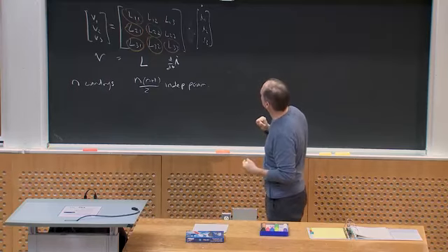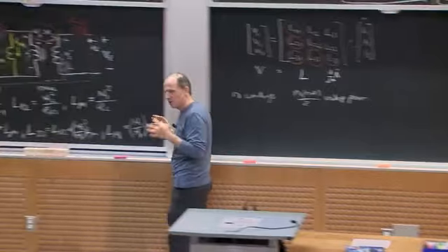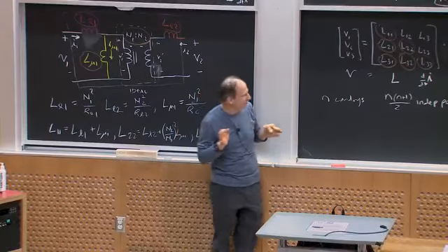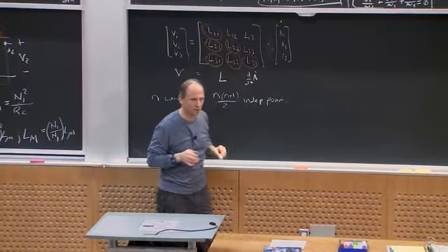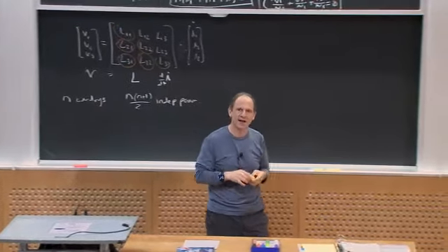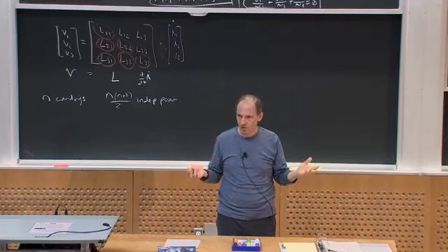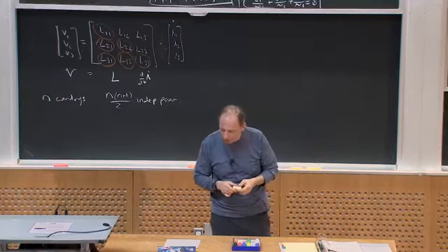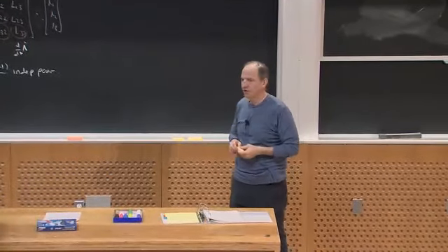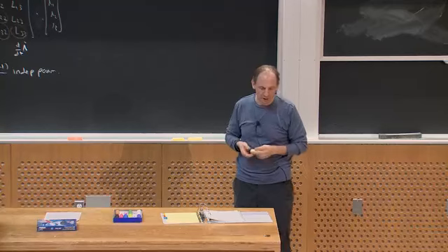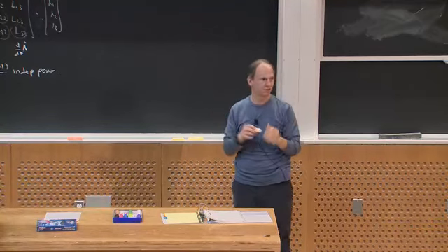Suppose I said, I'm not going to worry about getting a physical model, just give me a model that has just enough independent parameters to represent the 3-port or 4-port or 5-port network I have. There are in general a lot of ways you could do that. I'm going to show you one that I particularly like. It's called the extended cantilever model. It's by no means the only way to do it, but it's a very clean means of doing it.